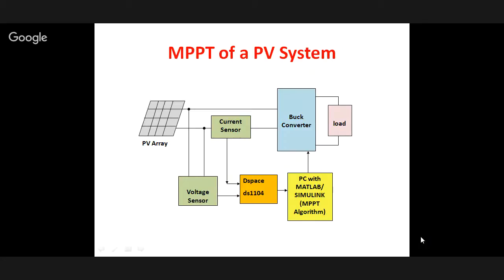So in that, you can see here we have the PV system. There is a current sensor, a voltage sensor. Acquiring the current and voltage, I am giving it to the dSPACE. This is just a DAC card, data acquisition hai. It will take the data to the MATLAB Simulink environment where I have written the MATLAB coding. Okay, from there it will generate me the duty cycle.